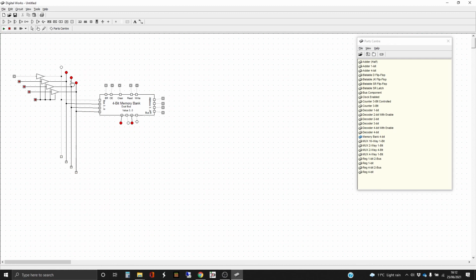So again, 2 phases. We need to read from the bus, which puts that into this I/O register, and then we're going to be writing, and we're going to put it into address 0001. Write the memory. There we go. So let's go back to 0000 and read that from the memory, and that should be 10. So that's 10 as we had previously.